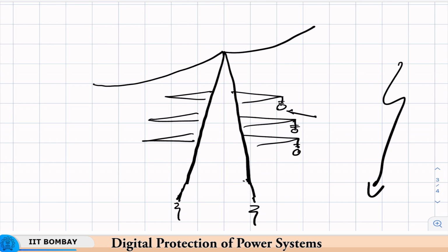So, the second kind of over voltage is when lightning strikes the ground wire here. Now, when it strikes the ground wire, a travelling wave will be set up. One part will travel towards this tower, the other part will travel towards the next tower. When it comes to the tower here, it will encounter a discontinuity.